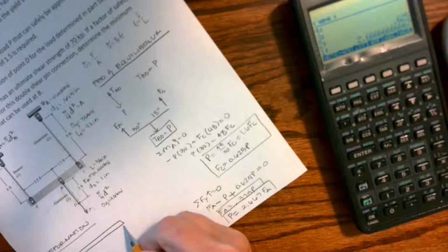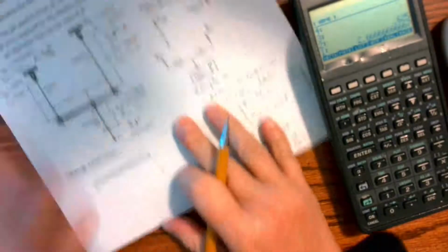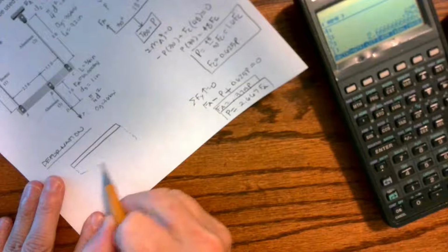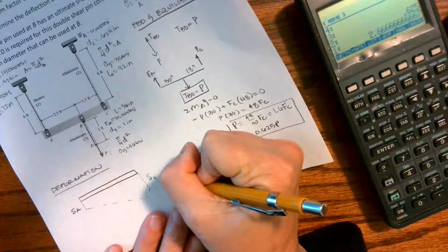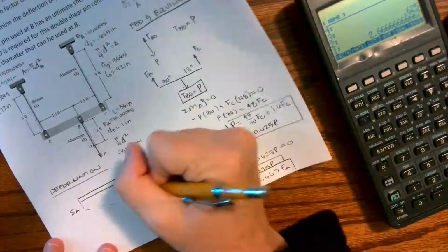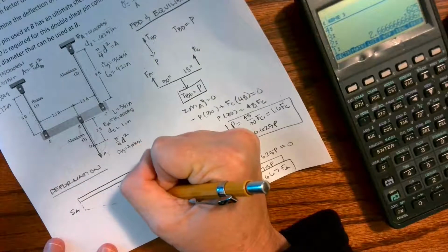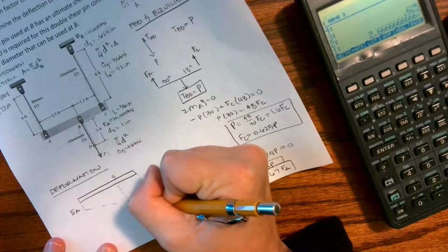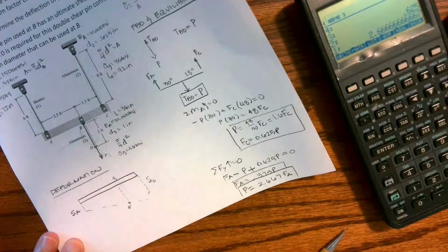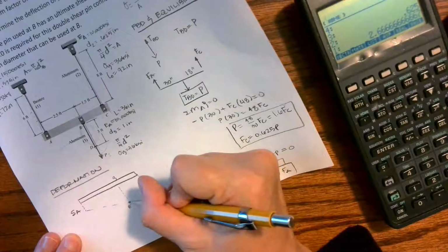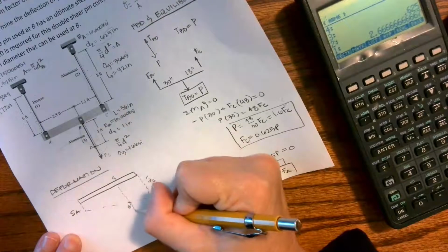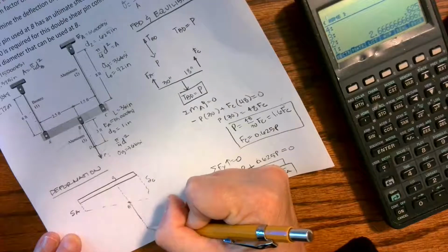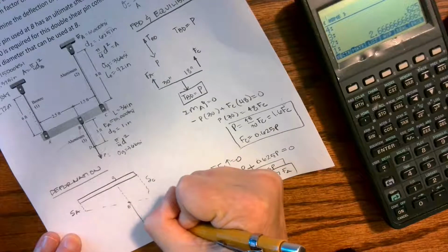So the whole system is going to come down, and we're going to have some deformation from cable A, and some deformation from cable C. Which means this point B is coming down from B to B prime. When I look at this tension cable BD, it's already been displaced by this amount. It has load on it, so it also has a stretch in cable BD.